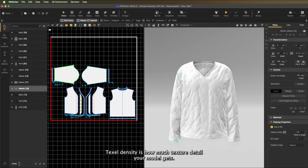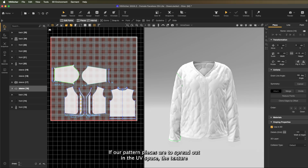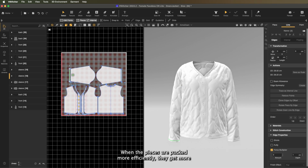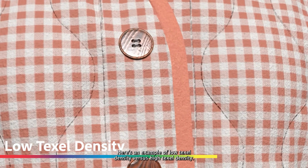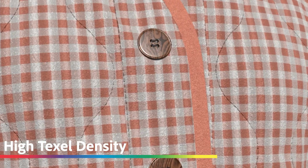Texel density is how much texture detail your model gets. If our pattern pieces are too spread out in the UV space, the texture has to stretch over a larger area, making it look lower quality. When the pieces are packed more efficiently, they get more texture detail, resulting in a sharper, higher quality look. Here's an example of low texel density versus high texel density.